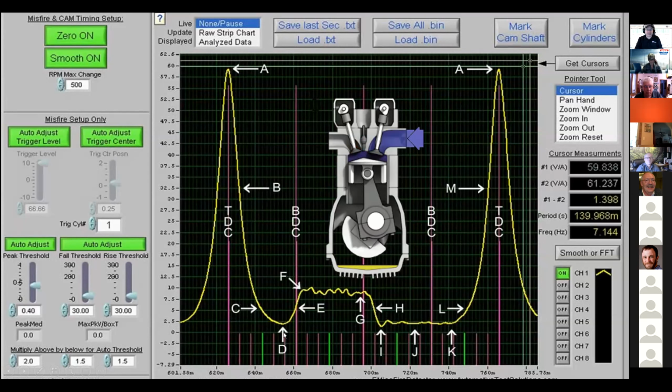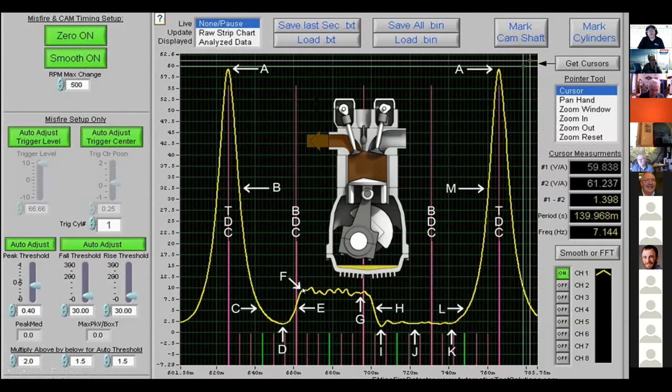Yes, it dictates things like cam timings, and I already told you in this class, I'm not getting into all these measurements. But the other thing that this test has the ability to dictate to you is the exhaust pressure. I could use one test to look at cam timing and exhaust pressure and quite a few other things, by the way, instead of doing multiple tests. So by doing this test, I get to look for that possible plugged exhaust. But here's where I wanted to keep this so simple for you.